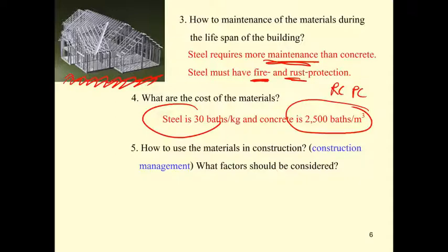But nowadays the concrete also has precast concrete, which can be produced in the concrete plant. So the pre-stressed concrete can be both RC pre-stressed and PC pre-stressed, and it's going to be high quality also. But the weight of it may be large during the transportation compared to steel. And the installation is also harder compared to the steel because the weight of it is a lot.